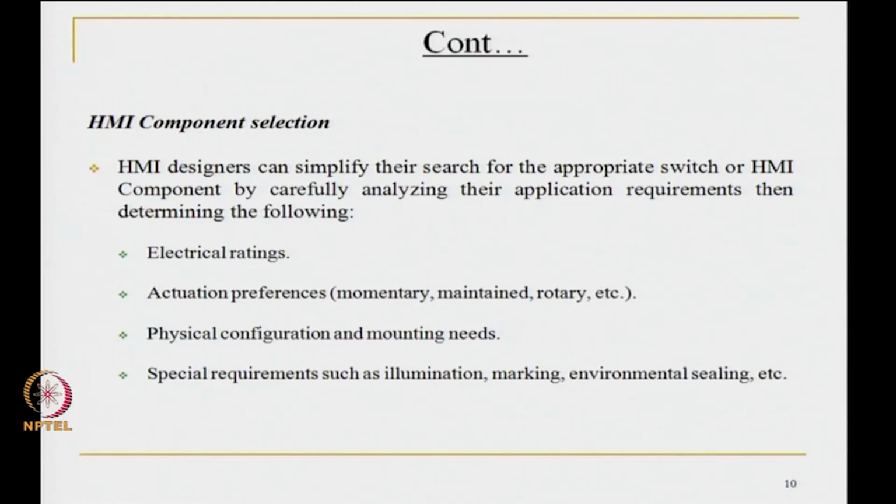If you determine the application requirements, then it becomes a technical issue, and the technical issue can be handled in the following manner. It can be handled through proper electrical ratings, it can be handled through actuation preferences, momentary, maintained, rotary, and physical configurations and mounting needs. Special requirements such as illumination markings and environmental sealing would help.